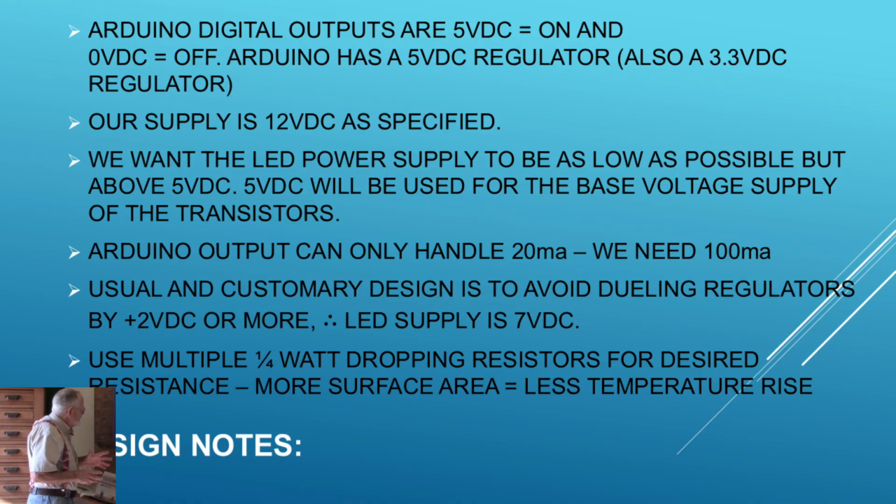A lot more components. Well, the problem is, if I need to drop a watt of power, V squared over R, or I squared times R, that's a big resistor, a 1 watt resistor. Because it has a relatively small surface area, you can't put a lot of them next to each other.